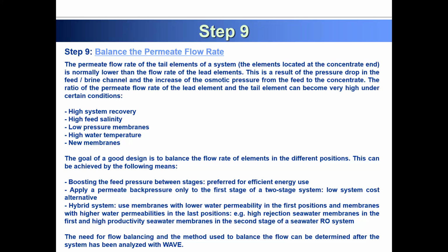So the ratio of flow rate of the lead element and the last element can become very high under these conditions: high system recovery, high feed salinity, low pressure membrane, high water temperature, and new membrane.